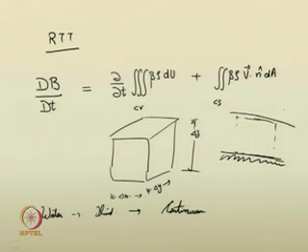Whatever the extensive property is, whether mass, momentum or energy, the material derivative of that extensive property in this control volume is equal to the amount of extensive property generated inside this control volume plus the quantity of this extensive property transferred through the control surfaces of this control volume.